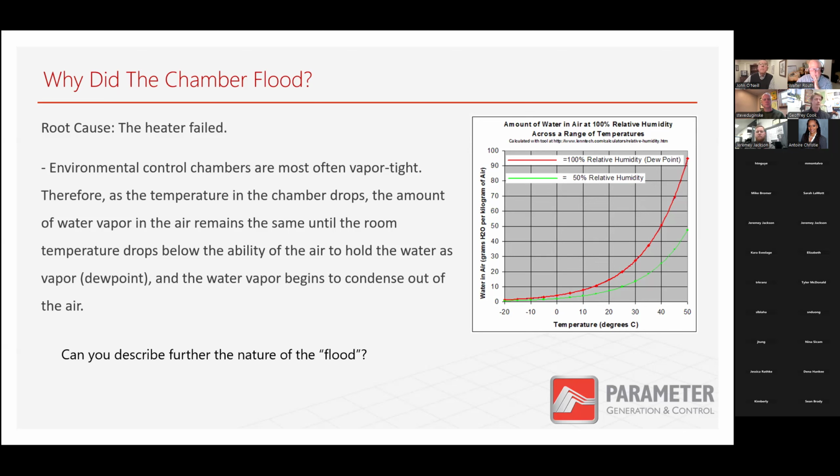Another really good thing to keep in mind is holding spare parts on hand. We like to keep a prioritized spare parts list based on the risk of the component failure, but also the impact and frequency of that component failure. And a lot of components have expected lifetimes. So you can keep some spare parts on hand, based on the expected lifetime of that part and also the risk and impact of a failure.